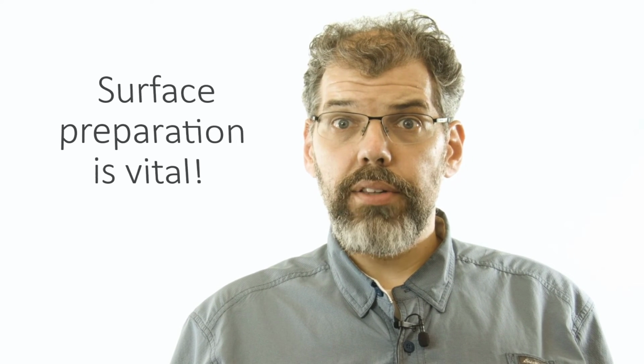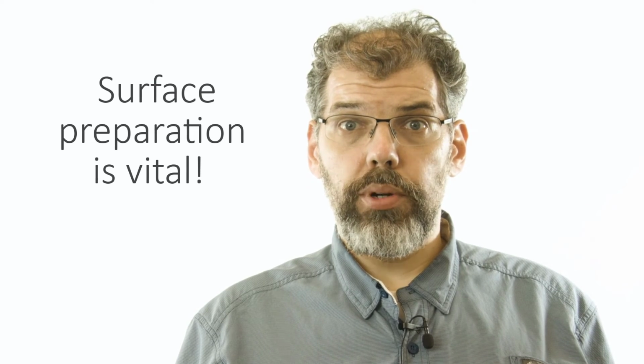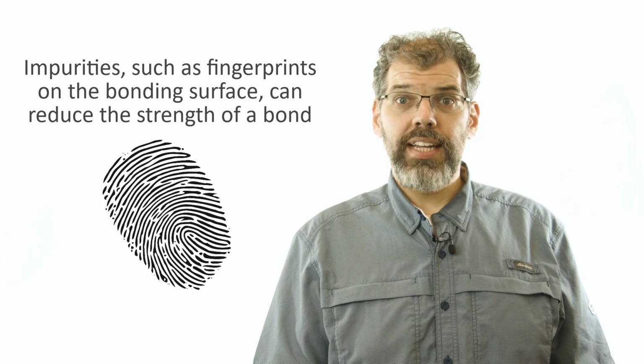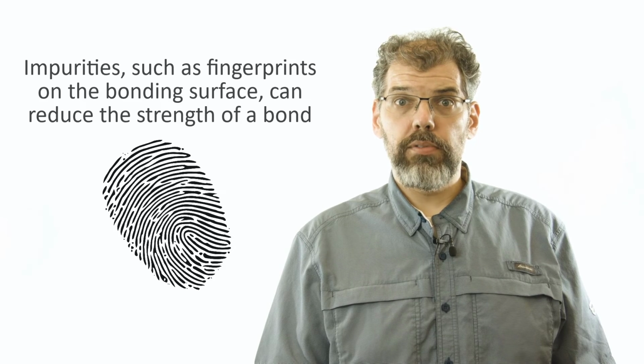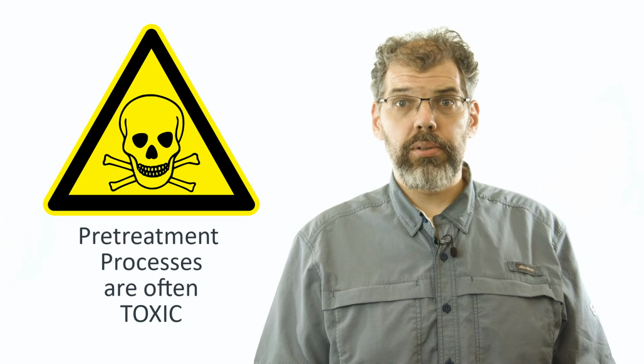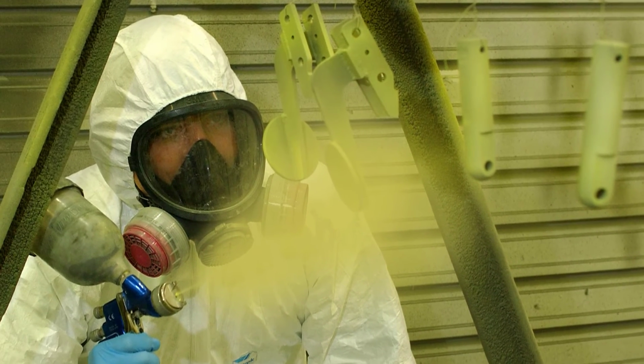From the description of the different steps within the bonding process, it should be clear that the surface preparation step is vital for ensuring the quality of the bond. Impurities and insufficient activation of the surface to be bonded can result in a very low adhesion strength of the joint, which is unacceptable for aircraft structures. Unfortunately, one of the challenges we face in the aerospace industry is that the pretreatment processes we use tend to involve toxic chemicals that are not good for the health of workers or the environment. We are constantly trying to find more environmentally friendly options, however, these tend to have a significant reduction in performance.